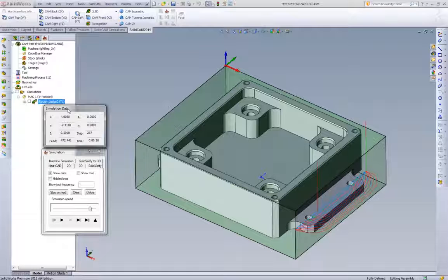So for customers that change materials a lot, cutting steel and aluminum, if you invest in 4-flute carbide end mills, you'll have great cycle times and great compatibility to switch between aluminum and steels very easily.